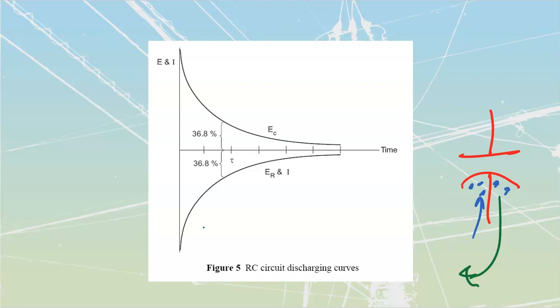And usually by the time that you found the panel, turned it off, and made your way back there, it's going to be a couple minutes anyways. But always just know that a capacitor stores charge, and if you don't allow it to discharge before you start working on it, you're going to be the path for that discharge current to go through. It's an uncomfortable thing, taking electrons through the skin.